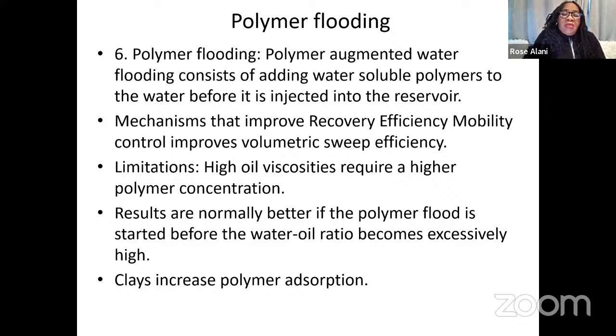There are some limitations. High oil viscosity requires higher polymer concentration, so if the oil is very heavy, you have to use more polymer. The results are normally better if the polymer flood is started before the water-oil ratio becomes excessively high.